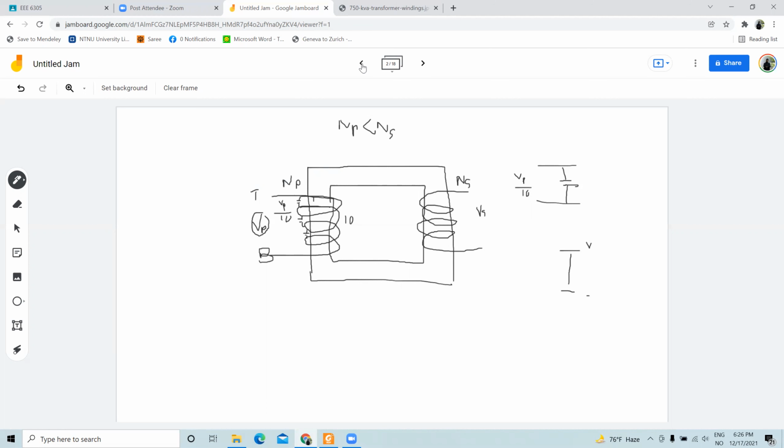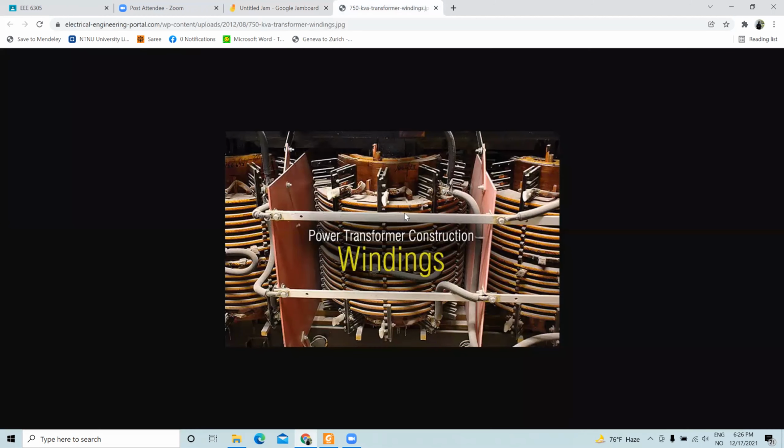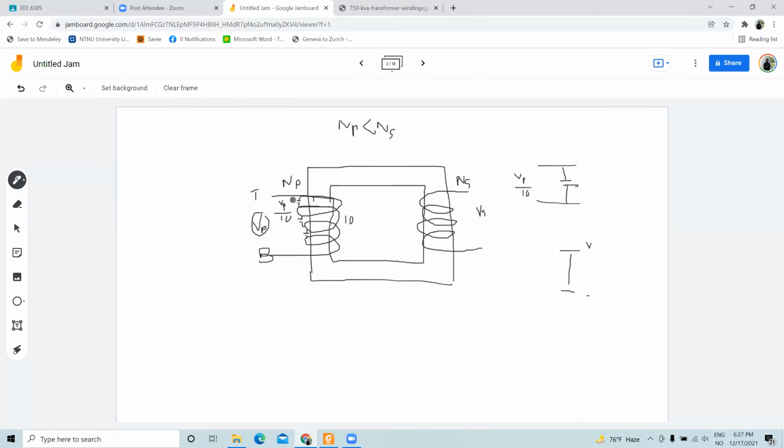Yes, sir. So the transformers will also have capacitors between each of these windings. Small capacitors that are not visible to your normal eyes, but of course, if you are an engineer, you have to see these capacitors. General people will not see them, but you understand that there is a capacitor between each of these windings. Let's say C is the small value of this capacitor.